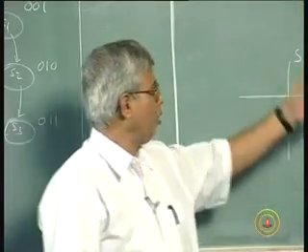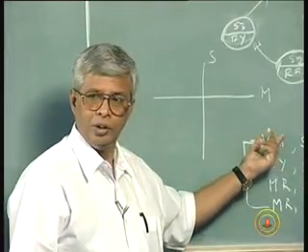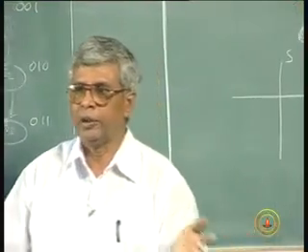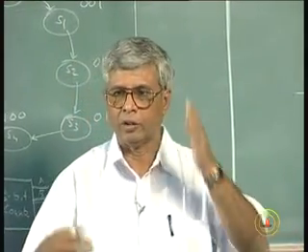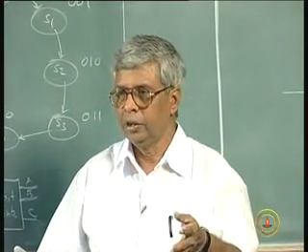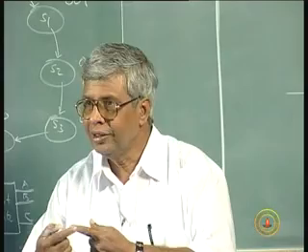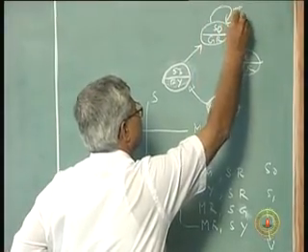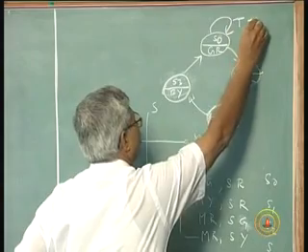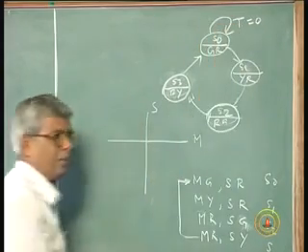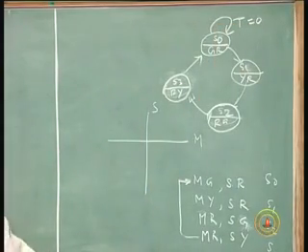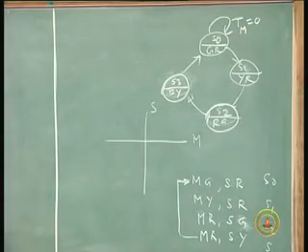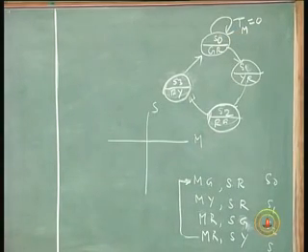On the other hand, I may want the main road signal to be longer duration than side road signal. Main road green has to be 2 minutes or 1 minute, and the side road can be only 20 seconds. In that case, I should put a timer and then say, if the timer, I will call it T1 as the timer for the main road, has not reached its value, it will remain in that state.